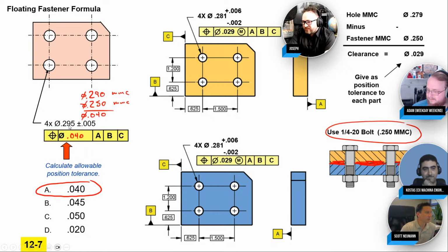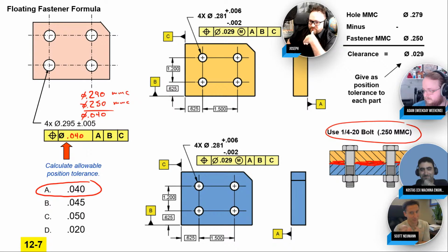And one trick I tell design people is you don't care about nominal. If you're a design engineer, you don't care about nominal. You care about worst case, smallest hole. Exactly. Smallest hole. That's so true. Smallest hole. Biggest pin, but smallest hole.